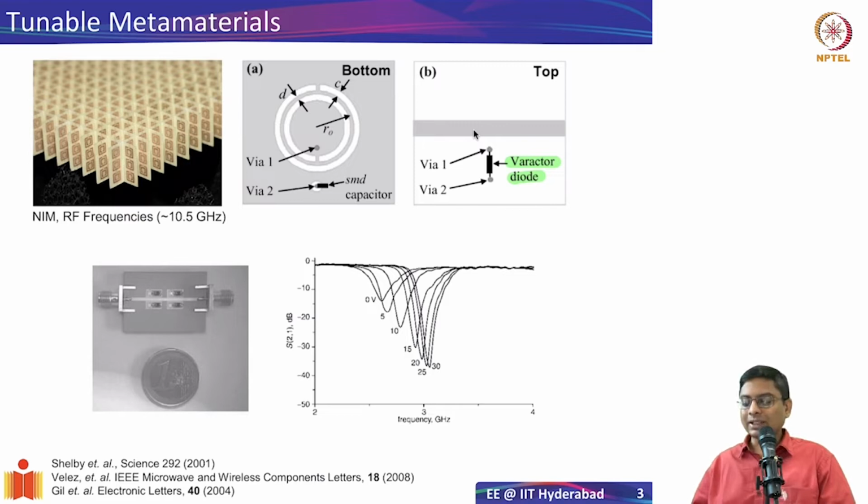So now I can connect a varactor diode across, let's say in this case, I'll drill a hole in the PCB, and then across 2 points I can connect them. This connection can be across this gap or this gap or this gap, depending on wherever we want. And various researchers have studied what is the optimal way. And we have also seen that the capacitance between the rings is what is going to contribute significantly to our overall C. So it will be beneficial if you actually put it across this and then tune the diode capacitance.